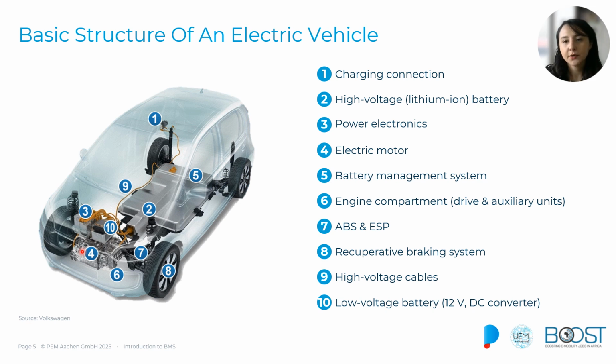Supporting the battery and the motor, in the middle we have the power electronic systems, and specifically the inverter. The function of the inverter is to convert the DC power from the battery into AC power for the motor. Without the power electronics in the middle, the energy transfer wouldn't be possible. Alongside the battery, number 2, we have of course the battery management system inside the battery, which, as I mentioned, is often referred to as the brain of the battery. The BMS has the function of monitoring the battery health and managing the energy output, and most importantly, ensuring that all of this operates within safe limits. It is crucial for preventing issues like overcharging, overheating, or cell imbalance, which can compromise the safety and performance of the vehicle.